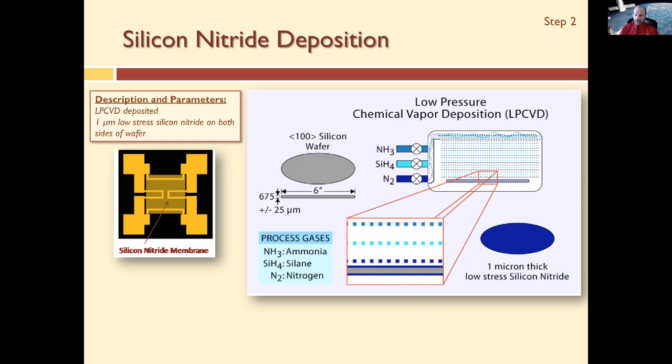And that deals with how well you can do your photolithography. So you want a flat surface if you're imaging something onto it. The smaller the structure you image, the flatter that surface needs to be. So yes, you can get different grades of wafers, different flatness grades. And of course, you pay more for them, right?